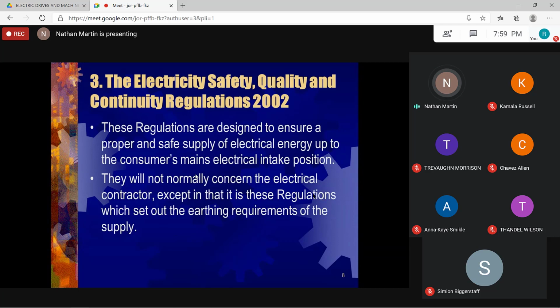Now, one thing I need to point out, this is beside the lesson. When a breaker trips, can anybody tell me how to reset a tripped breaker? You fully turn it off and then turn it back on. Okay, all right. So everybody hear that: you turn off the breaker first. A tripped breaker will be in the center. You have to turn it off before you can turn it on.